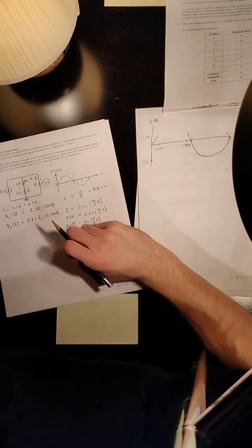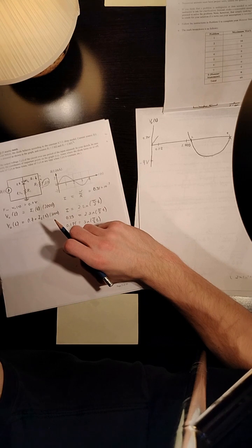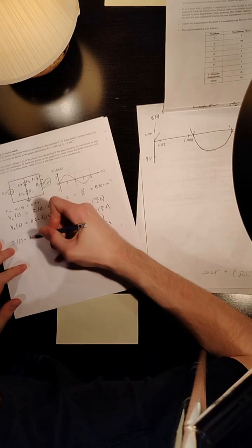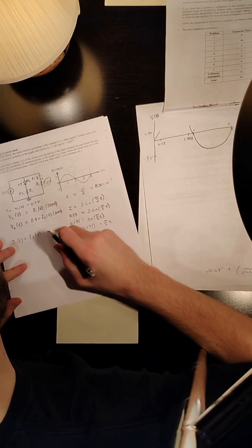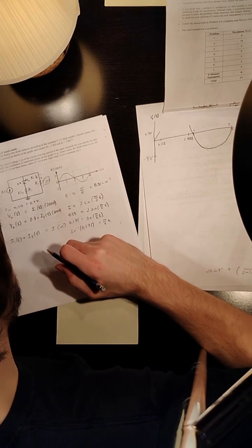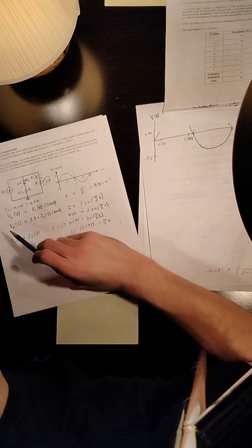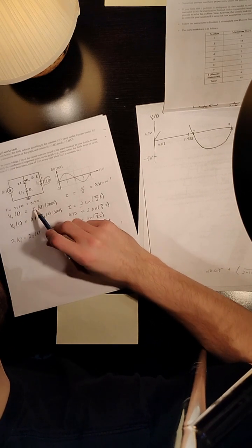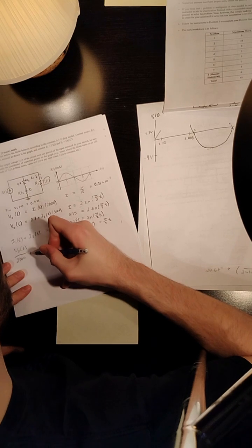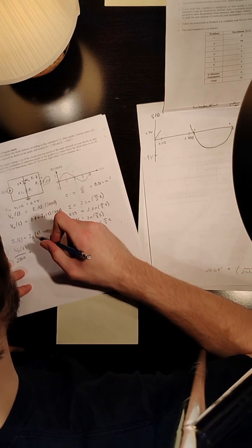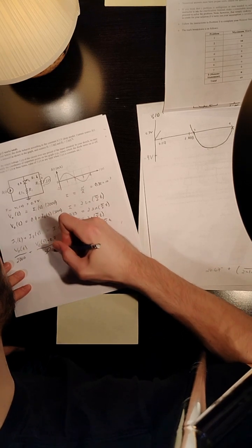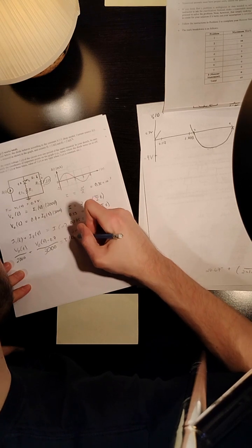And then we need one other equation, I believe, and that would come from the fact that I1 of t plus I2 of t is going to be equal to I of t. And then what we can do is make an expression for VO of t with respect to I of t, because we would have VO of t over 2000 plus VO of t minus 0.7 over 3000, and that's going to be equal to I of t.